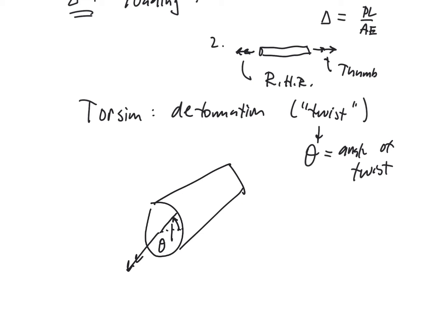And so you've got to be a little bit careful about the words that you use. So remember, torsion is linked with a type of deformation, and that is there's an opening up of the angle. It was here, now it's here. So it's no longer at 90 degrees, and that is basically then the shear strain. And that shear strain leads to a shear stress that balances that applied torque.